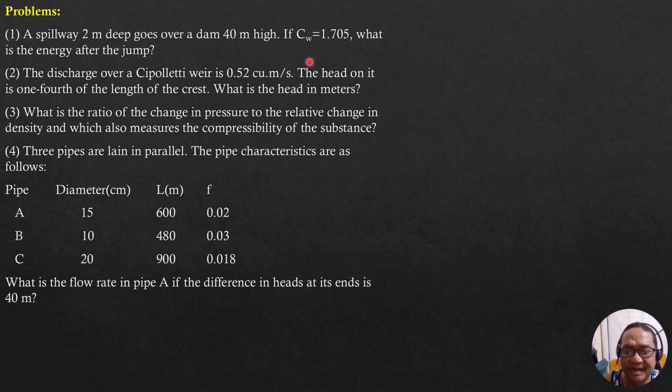The head loss in the jump when the channel is rectangular is equal to depth 2 minus depth 1, quantity cubed, divided by quantity 4 times depth 1 depth 2. And you just refer to the derivation in open channels about hydraulic jump when the section is rectangular. Of course, this is a rectangular channel. The spillway or the dam may be treated as a rectangular channel.